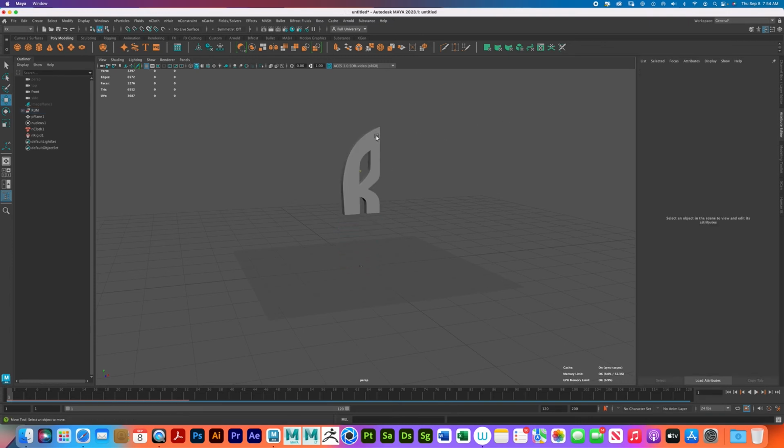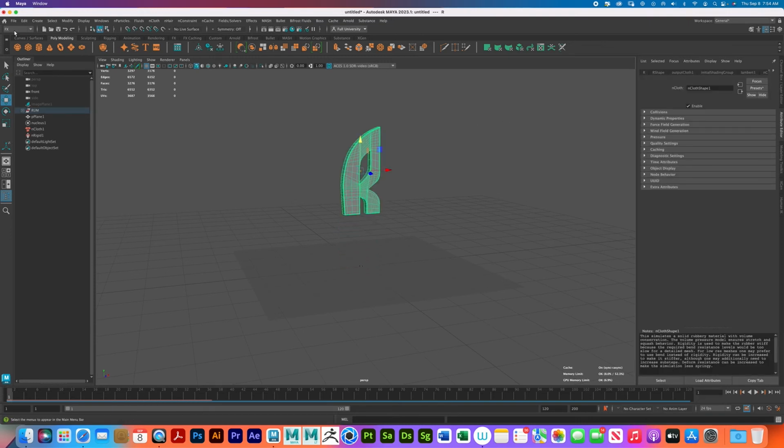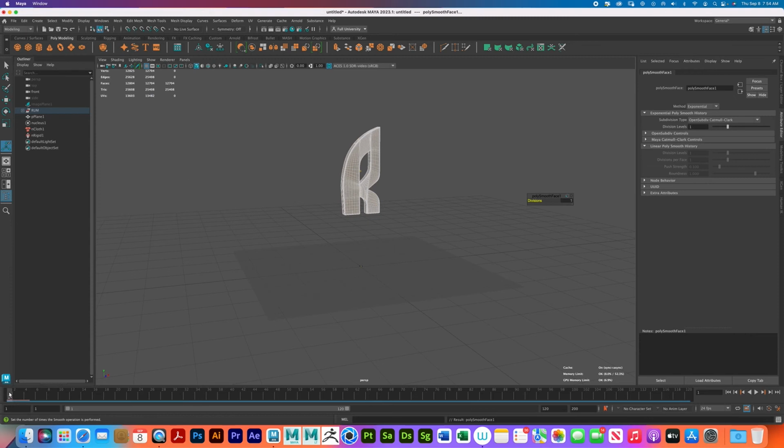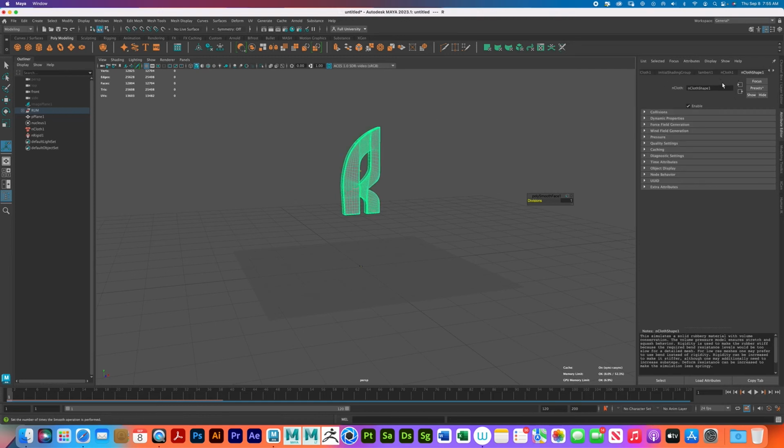You know how we can fix this? Let's go back to modeling, mesh, and let's add more geometry, see what happens. And now let's try this. Sometimes if it wrinkles up like that, it's because it does not have enough supporting geometry and it'll fall apart. And that's what happens. But let's say, look at the difference. Boing. You see that? It did not show all those little black parts that came up when I first did it, because now it has more supporting geometry.